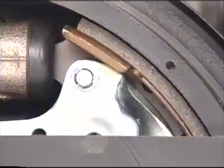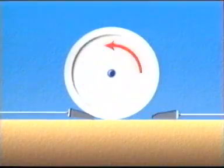The trailing shoe tries to push against the force, while the leading shoe is pulled into the revolution and produces a larger brake force. The increased braking force is called the self-servo effect.